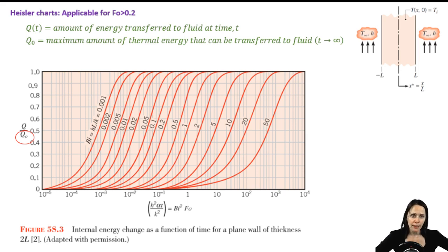And apply my first law of thermodynamics, or my energy balance. I see that Q naught is equal to the change in internal energy, which, assuming constant specific heats, is equal to m times specific heat times the temperature change. Note that I've written the temperature change so that I'll calculate a positive number if the wall is cooling down. If it were heating up, you could calculate a positive number just by flipping those.